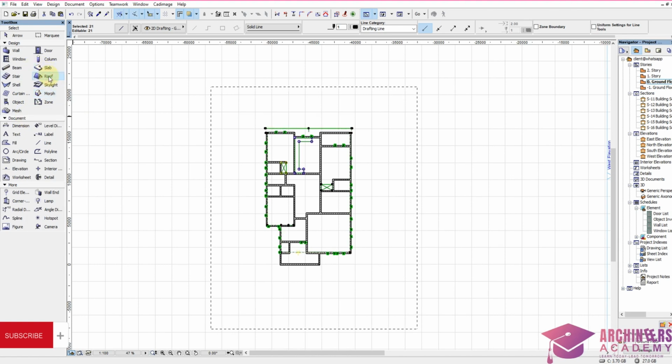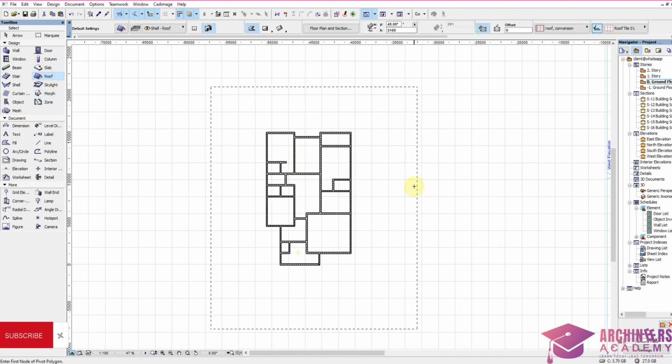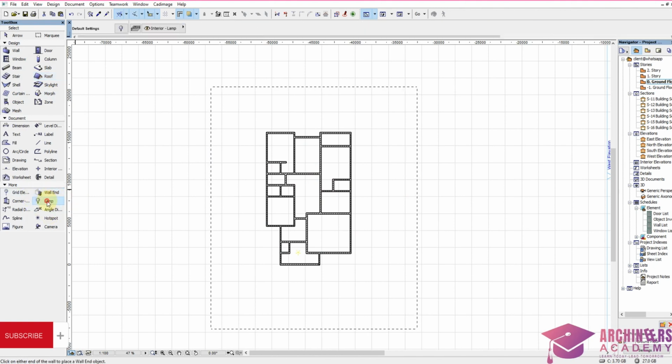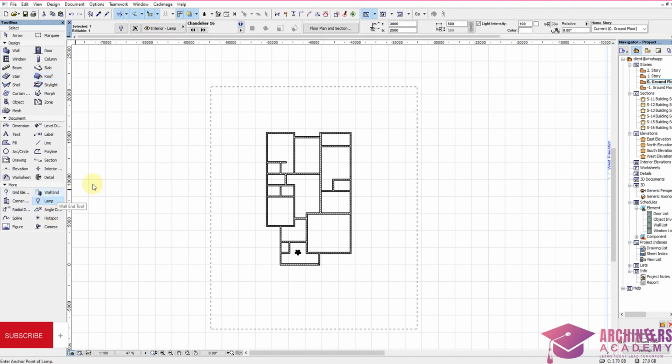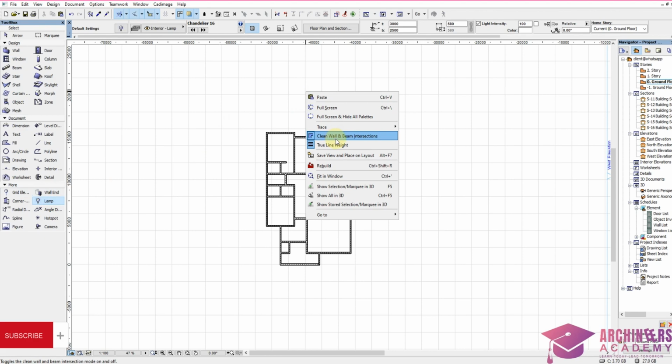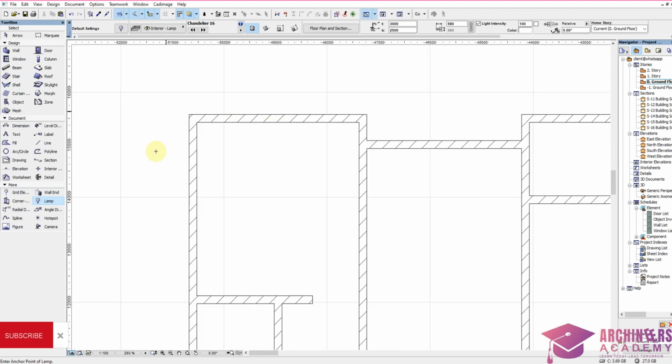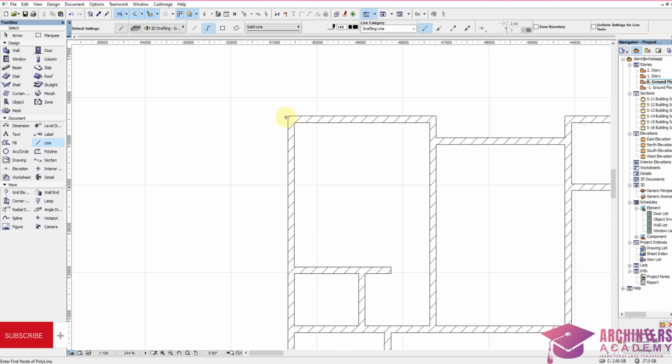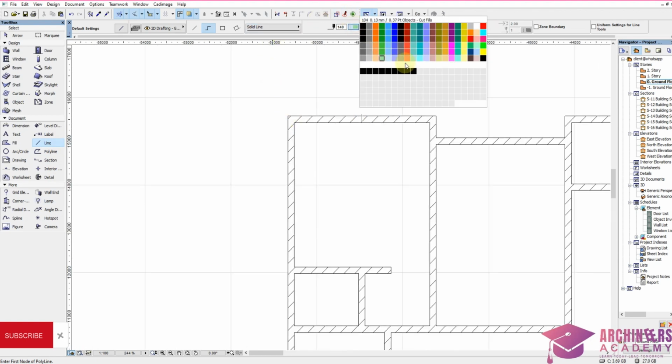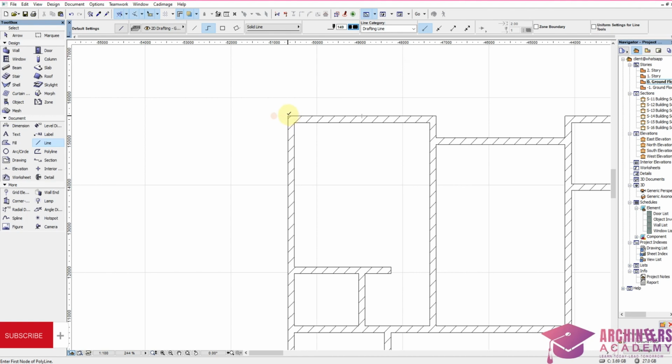Then I'll make it just only the line there, Ctrl A, and I can make this to be through line width again. Then I'll make it a line. I want to place my building, and my building should be in a line format. So I'll make this the thickest line I have, which is 3.00 millimeter. Then I'll use it to trace the building, making sure that it is on chain geometrical method.